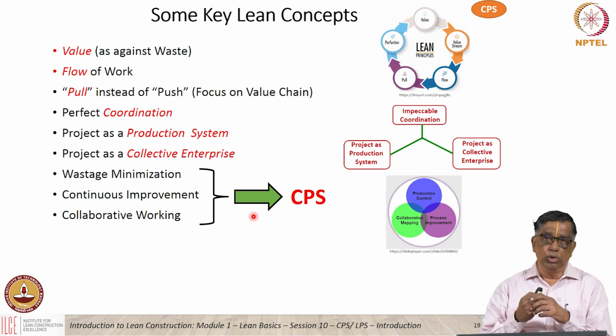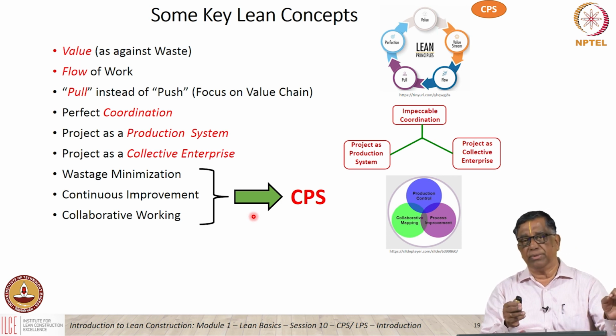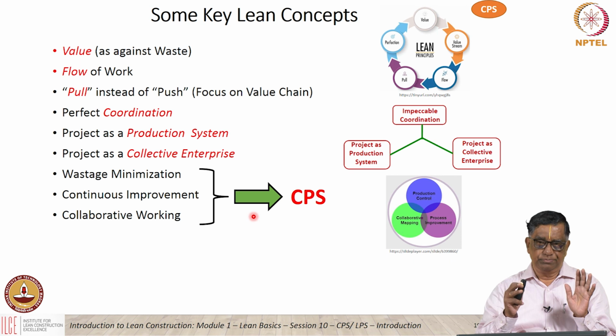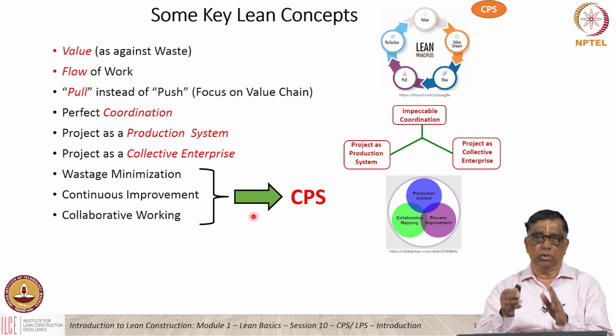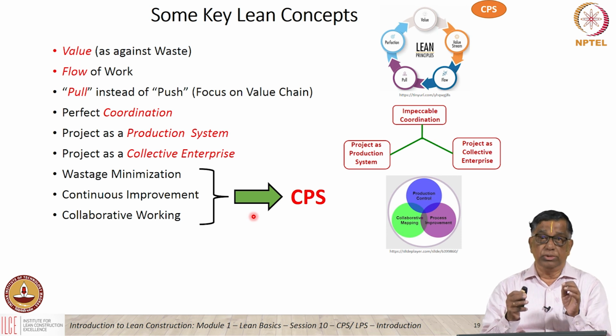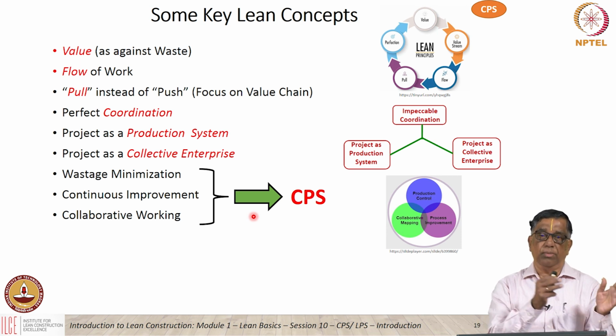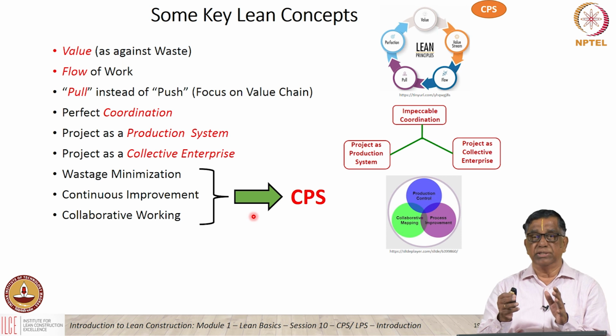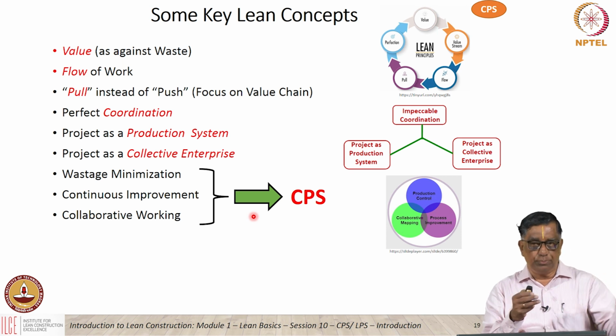But if you adopt a pull approach, the concreting man dictates the sequence. He says, today I require so many tons of rebar of the various types. Tomorrow I require a different quantity and so on. And the rebar man produces according to this kind of requirement. Then whatever he produces is going to be utilized gainfully. That's called pulling the work.